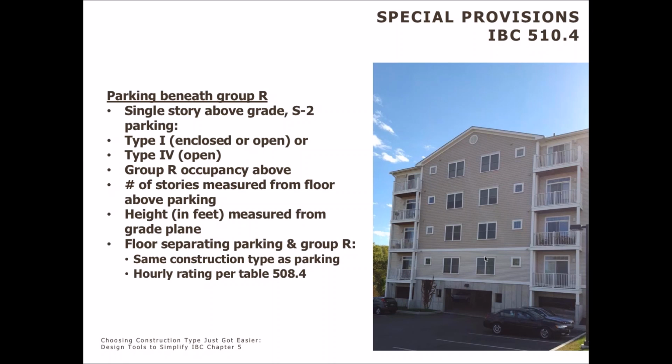The benefit here and the difference that this one has compared to the podium provision is that we aren't required to go full type 1A construction for that parking level, and we're not required the 3-hour separation that the podium provision has. Here we're just using, it's usually either a 1 or a 2-hour separation, depending on which construction type we've used, as well as if the building is sprinklered or not.